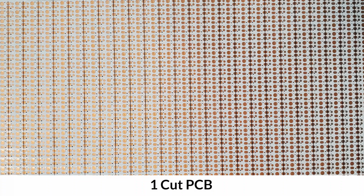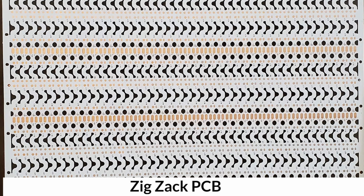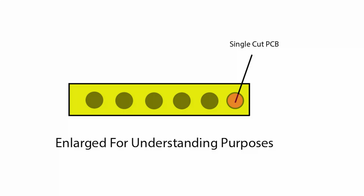We are proud to say that we have come up with a solution to this unique problem with a single cut PCB. As in, if this problem arises, we take the single cut LED strip which can be placed specifically on the corner of a profile. We match it with the color temperature of the strip that has already been placed on the profile, and hence there are no dark spots on the edges.